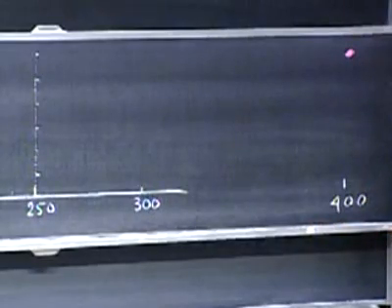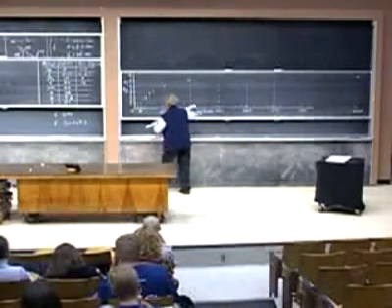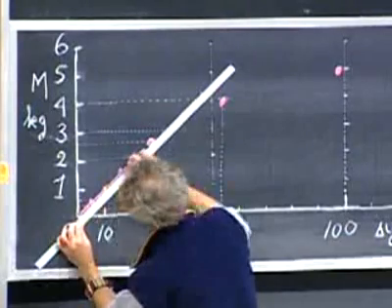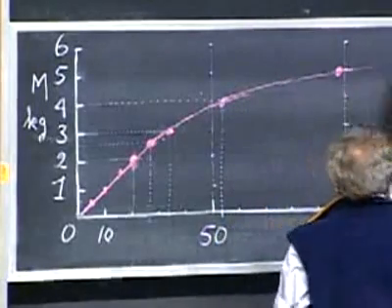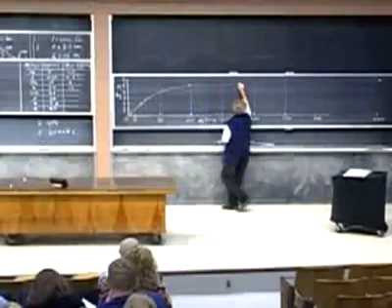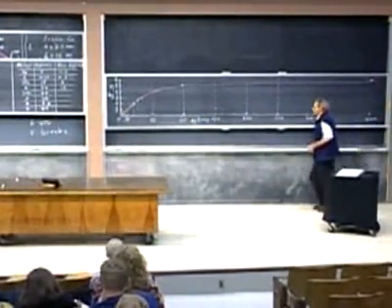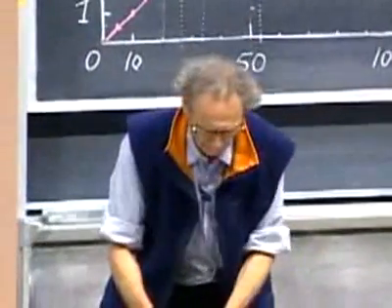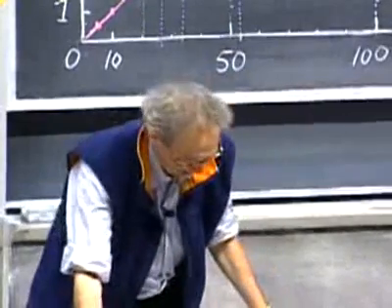And then we don't have the rest. But look how wonderful this is, isn't it? Isn't that a great curve? Very linear in the beginning. And it starts to bend over, and you draw that line any way you want to. And then it breaks. And so we can now actually make an attempt to calculate Young's modulus from the data. Of course, you'll have to select a portion where you think that the data are reasonably linear.